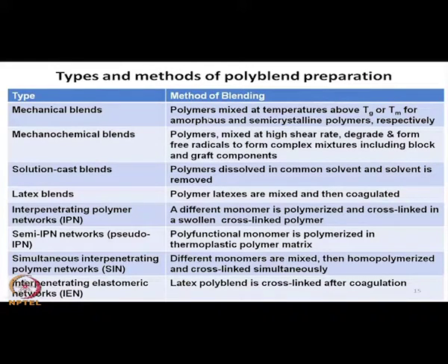If the two component polymers are amorphous, those two component polymers can be mechanically mixed in mechanical blenders, like a polymer mixer, say a 2-roll mixer or an internal mixer, by heating the polymer above their glass transition. Above their glass transition, the polymer will become soft and flexible, and then those amorphous component polymers can be mixed.